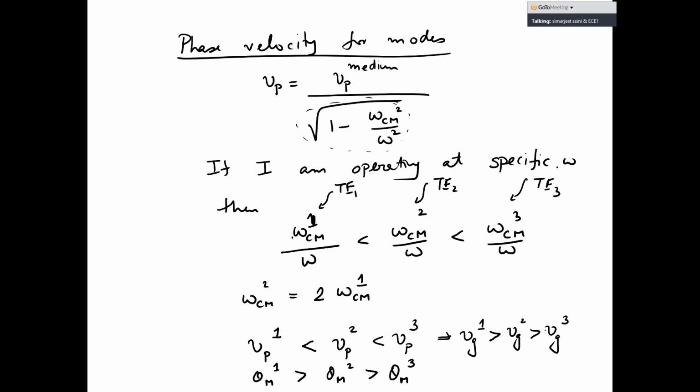And as we do rectangular waveguides and throw questions at you on that, you'll realize that when we do communication, most of the time, whether it is with rectangular waveguides, metallic waveguides, or dielectric waveguides like optical fiber, we want to design the waveguides such that only a single mode can exist inside, only a single solution exists inside, so that the waveguide dimensions or the frequency are below the cutoff frequency of the second order mode. And we'll do these questions later on.